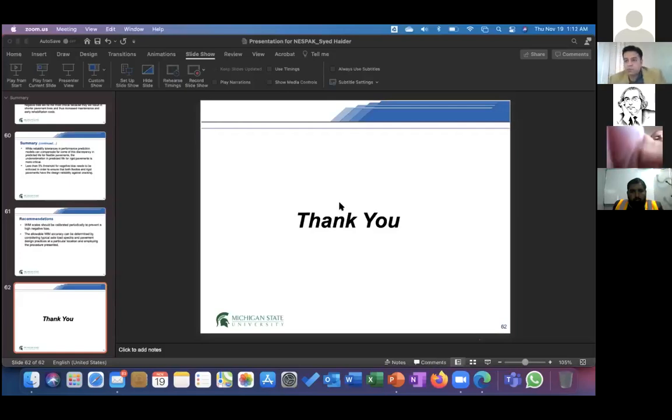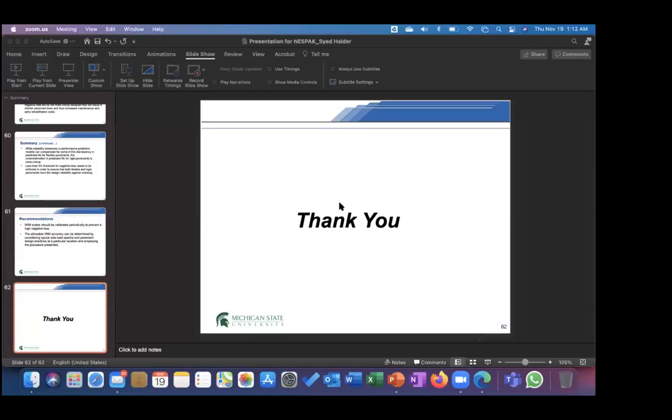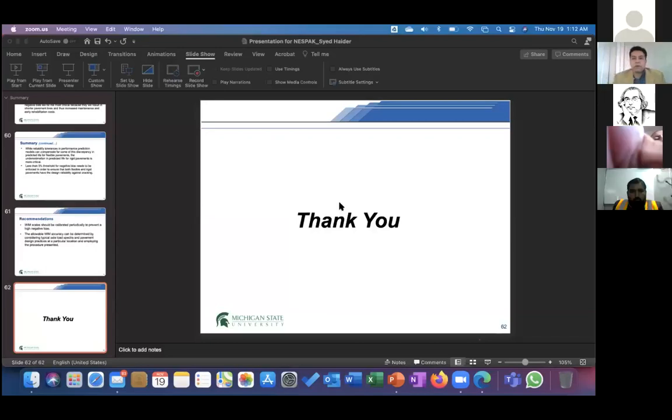So I talked about the site selection, right? When you select a site for WIM sensor installation, it has to be a new pavement. You don't want to install a sensor which you are going to overlay or rehabilitate in 2 years, because then you have to replace the sensor. The site has to be on a straight portion of the road. We don't want to install it on the curves. Your grade should be less than 2% because we don't want to install it on a higher grade. So there are certain criteria for selecting these sites.